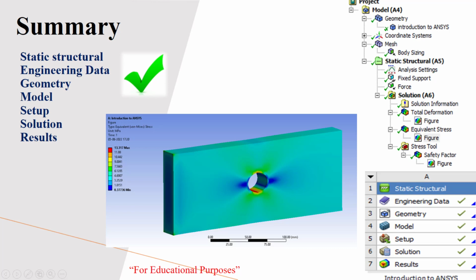So whatever the regions you are seeing in red, it shows that there the maximum mesh stress is located, not the failure, remember that. Okay, and then we have gone through the sectioning, probing, and the report generation as well. So that's all about the basics of ANSYS user interface and the basic simulation and how we can conduct it on the ANSYS user interface. Okay, well, thank you all.